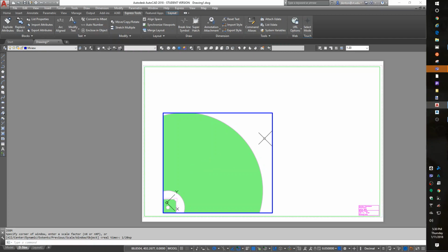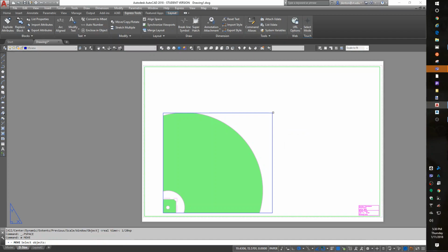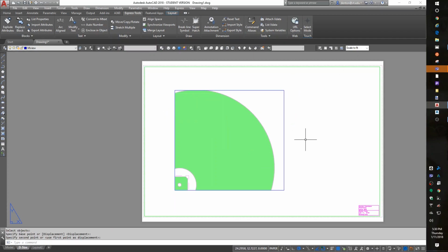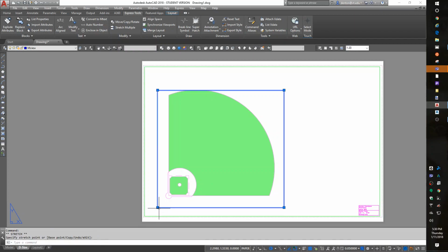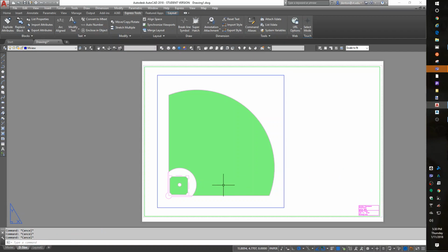I like 20 scale, but my mview is not big enough. Well, I'm going to move my mview up a little bit, grab the bottom corner of it and make it a little bigger. Grab the top edge, make it a little bigger. I like that much better. Escape out of that. An mview is just an object. I can copy an mview and just put it somewhere else.